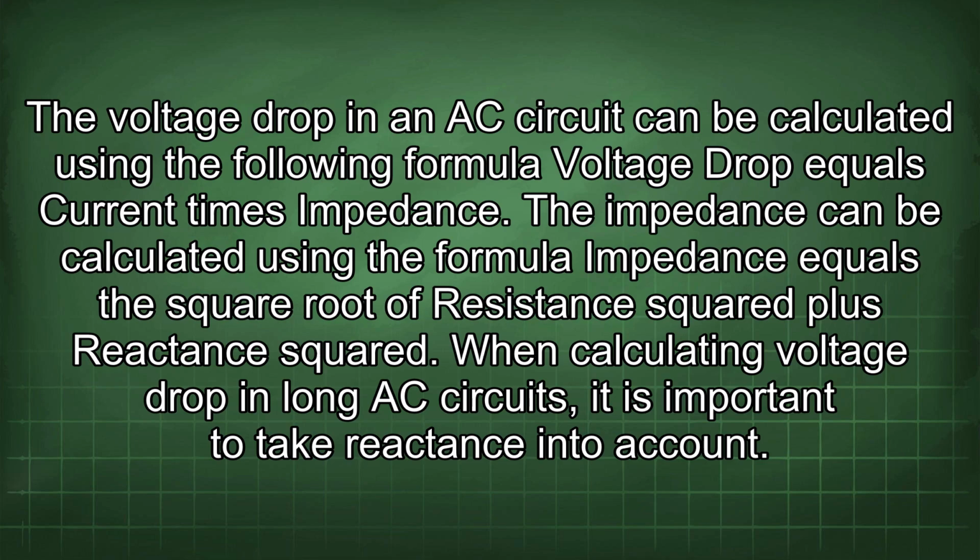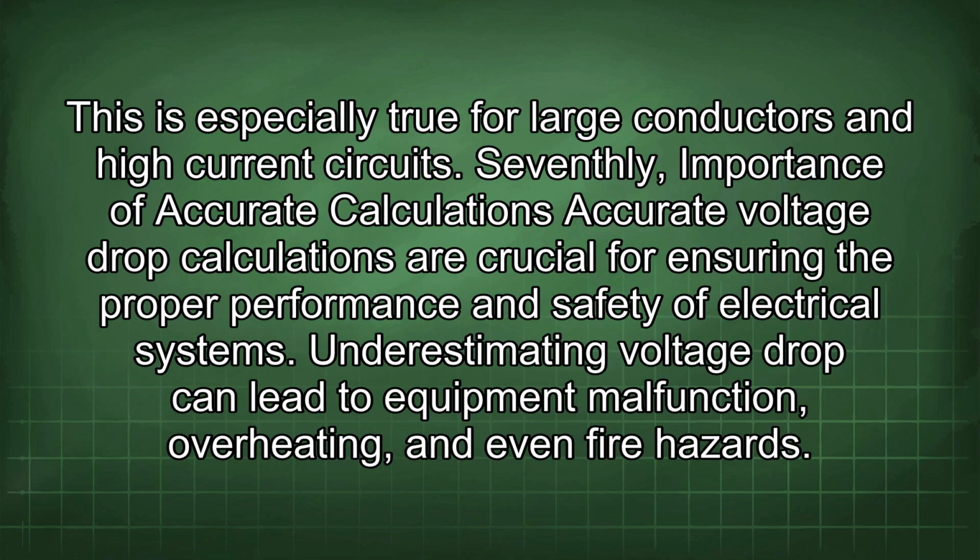When calculating voltage drop in AC circuits, it is important to take reactance into account. This is especially true for large conductors and high current circuits. Seventhly, importance of accurate calculations.